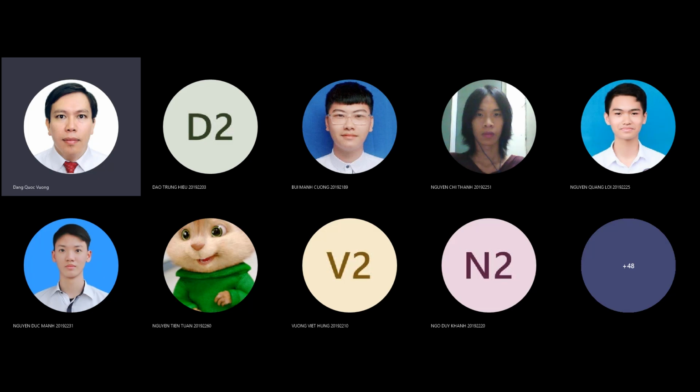Okay, and of course, for the capacitive load, you can see the voltage drop is negative. It's negative without being positive. So that's the reason why, when we connect to the capacitive load, the output voltage of the transformer is higher than the rated voltage, because this concept you know already.